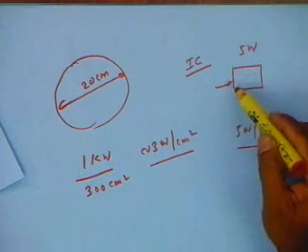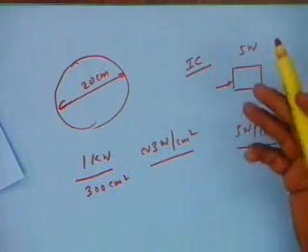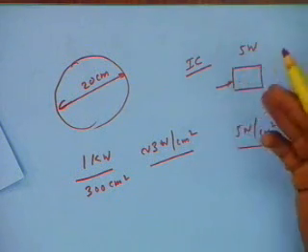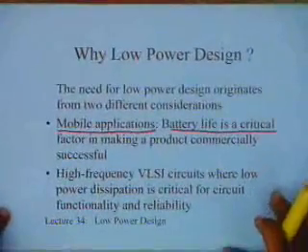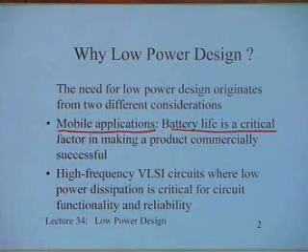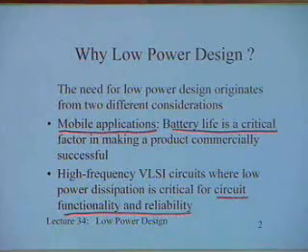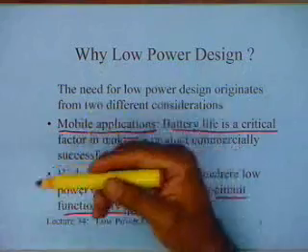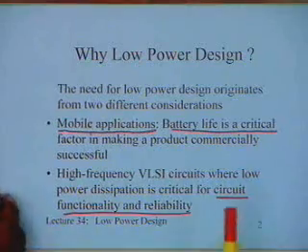That essentially means that something which gets so hot obviously has problems of reliability. Even the conduction properties change considerably if a device becomes very hot, and it is also prone to failures. So just from the point of view that power dissipation is so high when you pack so many transistors in a small area, it is critical for both circuit functionality and reliability. So one is talking of low power design not just from the point of view of mobile. Of course, mobile is very critical, but even from the point of view of high frequency VLSI design, low power is an important criterion.